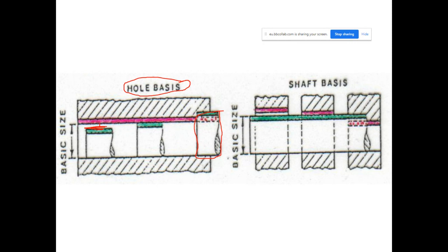If you decrease the diameter by cutting the material, applying a turning process, for instance, if it is a cylinder, a turning process. If it is a right prismatic object, then the material is to be removed from a surface to have a flat surface in the correct size in the end. Then using a crank shaper, a milling machine, or a planing machine, we can cut the material and have, for instance, a slide fit. If you need a clearance fit, then cut the material further and have the clearance fit.